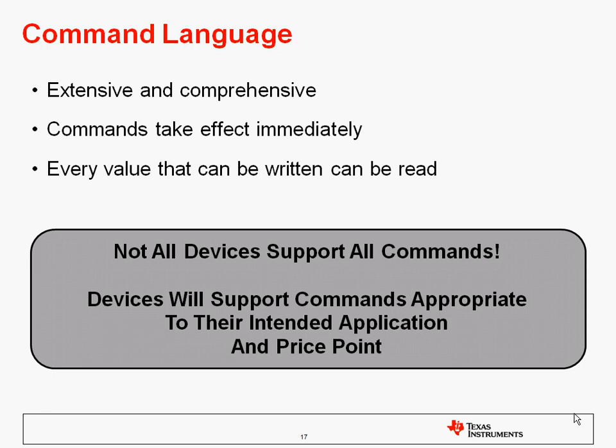This would make products probably more expensive than they want to be, and certain commands just don't make sense for certain types of devices. So basically, the PMBus command set has more than 100 commands, but what you'll find is that most parts will support 10, 20, 30 relevant commands that make sense based on the application, the price point intended, and how customers want to use it.